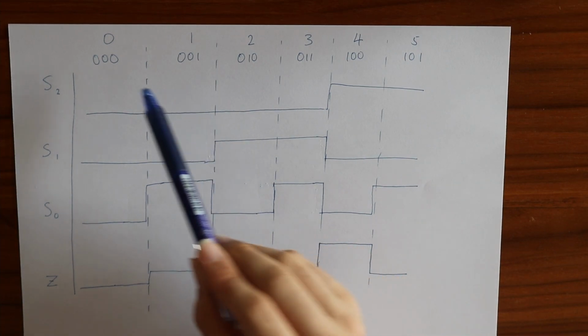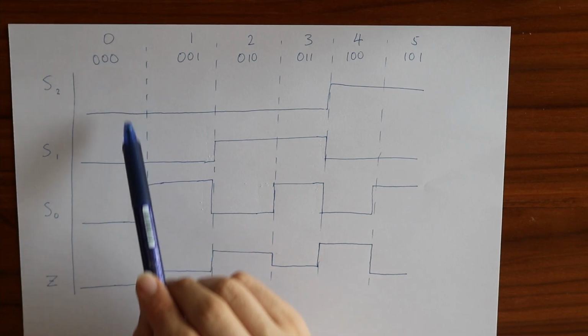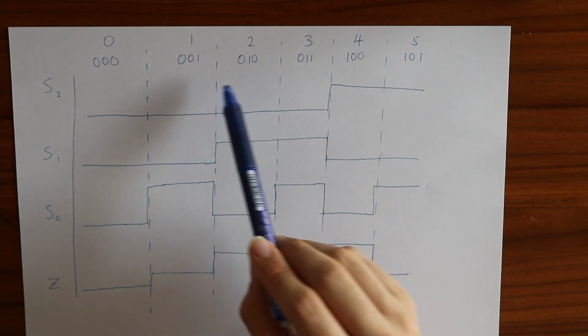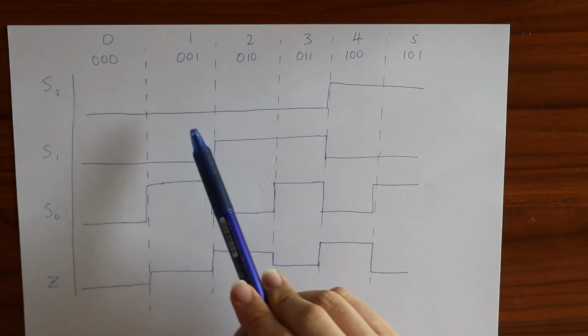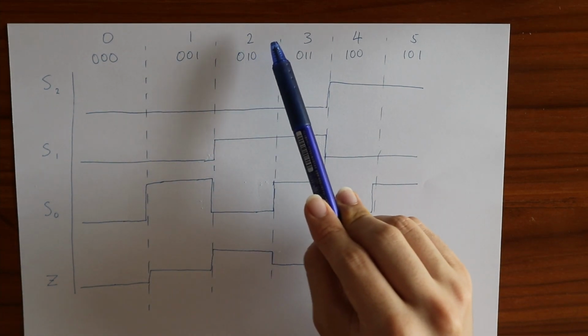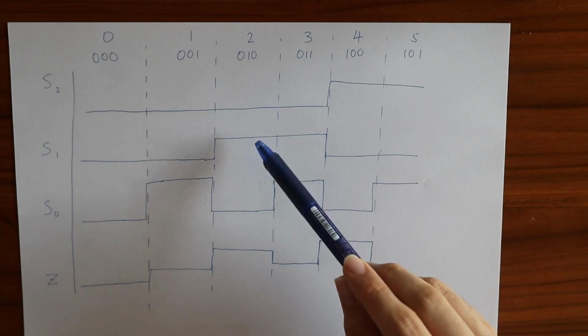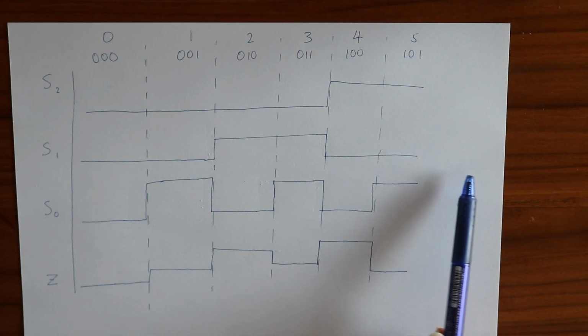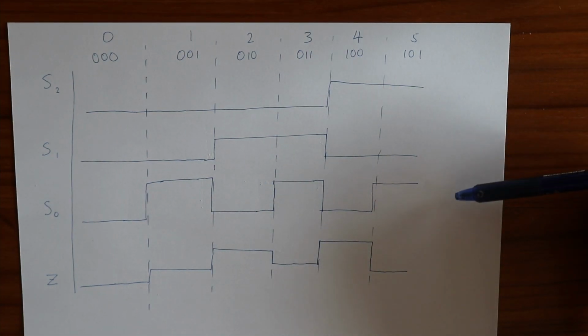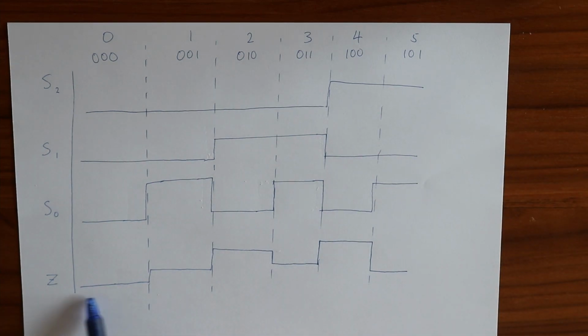You can see when it's trying to reference pin number 0, it's 0, 0, 0. When it's trying to reference pin number 1, it's 0, 0, 1. When it's trying to reference pin number 2, it's 0, 1, 0, and so on and so on. After the appropriate voltage is set, the returning analog voltage can be read.